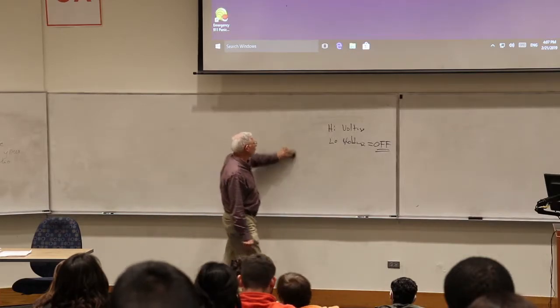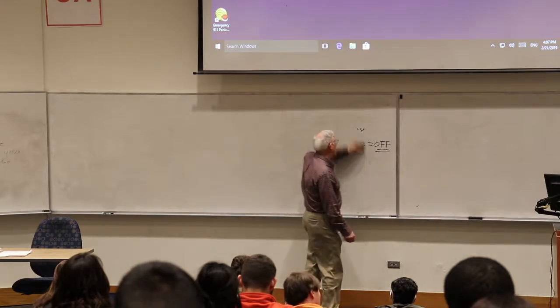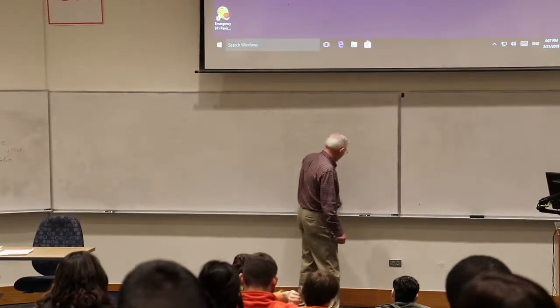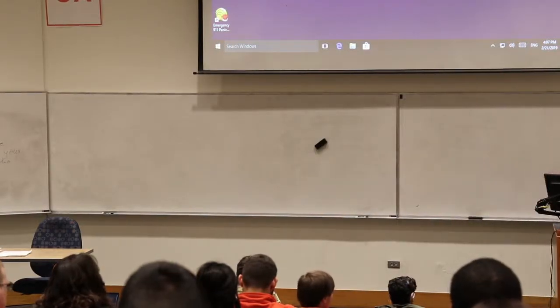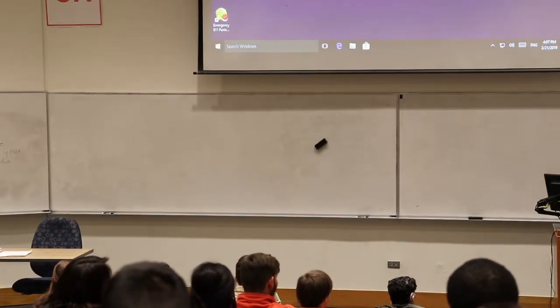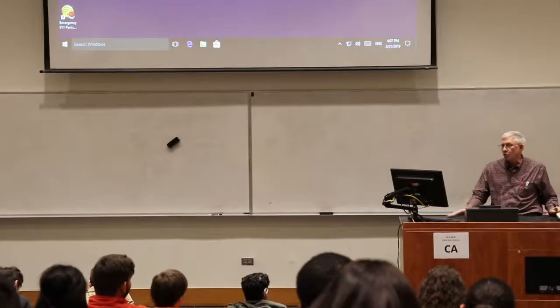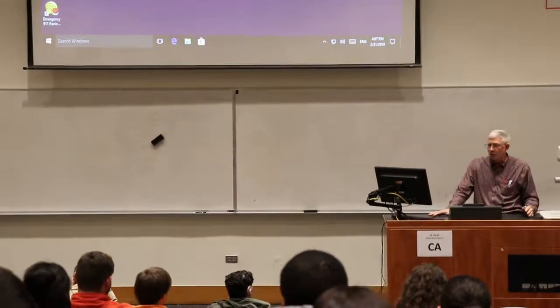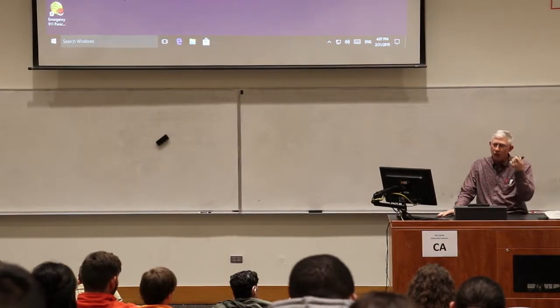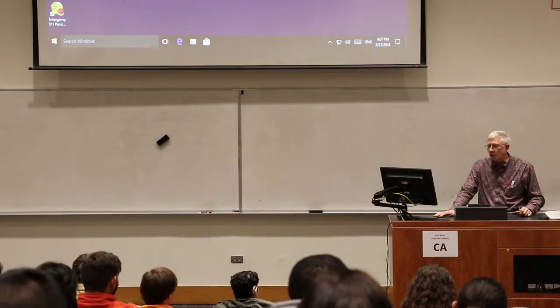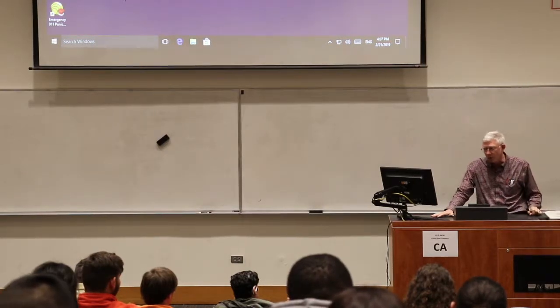Otherwise the snap's a great thing, and it's a lot cheaper than the Picket 3, which they've discontinued anyway. And it programs faster, it has most of the same features, but a few of them it is missing. And the two that are missing, it can't power the board, so you need to have your battery, or you need to have a little USB cable with the 2.5 millimeter plug put on the end of it so you can power your board.